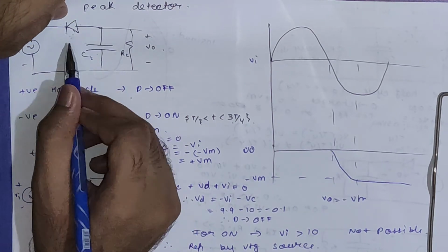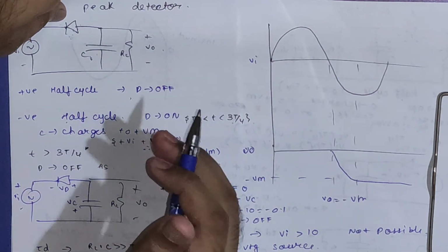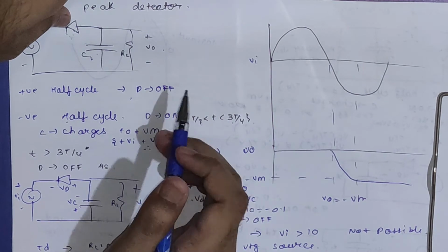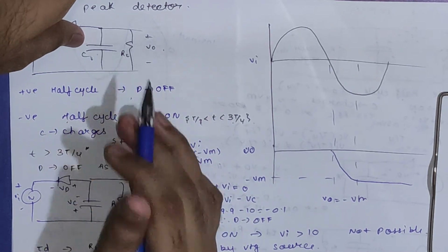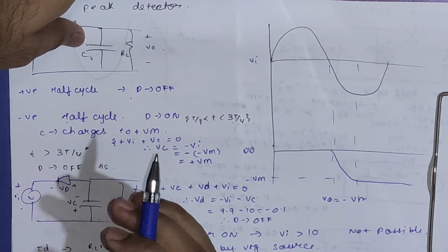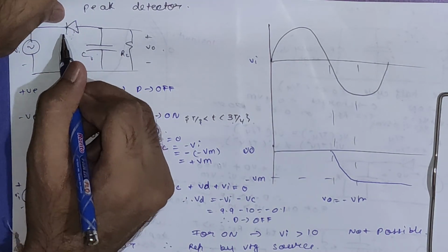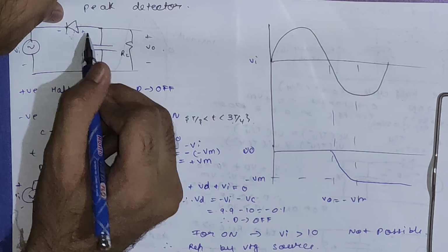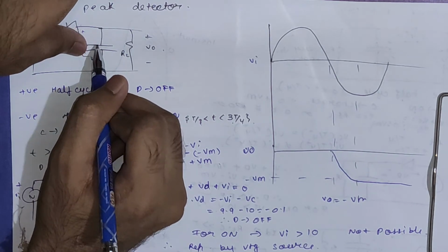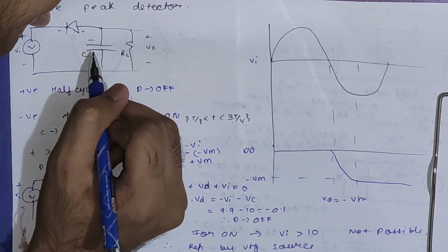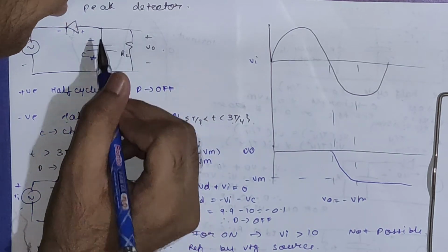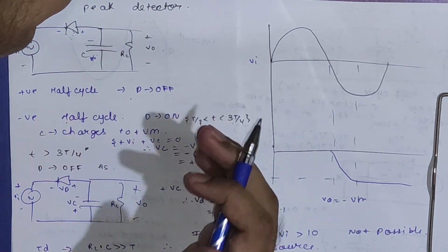As we know, the diode resistance can be RF or it will simply be 0 ohm. Okay, so the charging time constant for the capacitor will be very small, so we can say the capacitor will be charged. The polarity will be similar to the diode polarity. You can see we have first minus then plus, so the polarity of the capacitor will also be the same, that is minus first then plus. We know the polarity right now, we want only the magnitude.